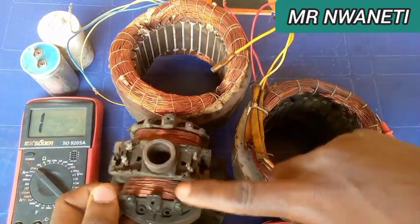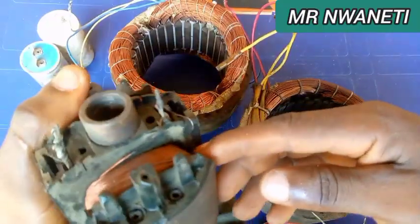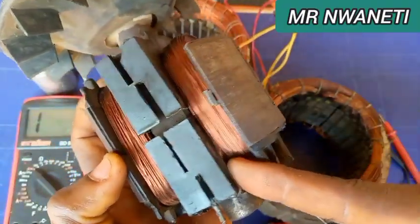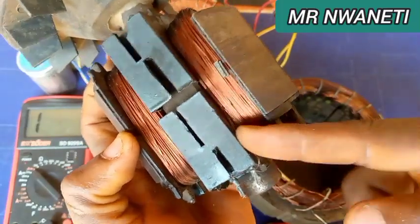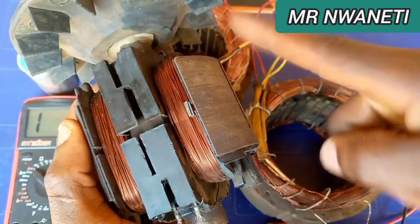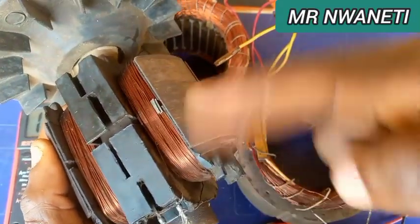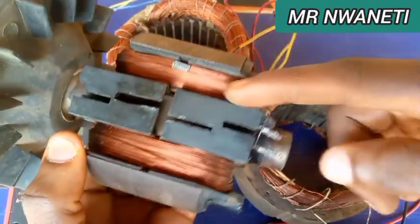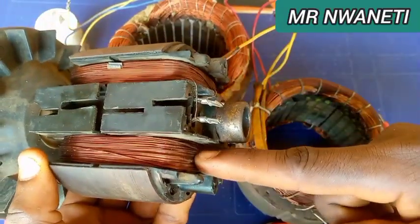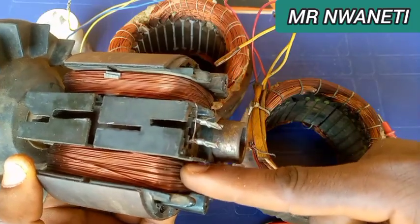So now assuming you want to have more voltage, you can see this is the continuous winding, so you have to loosen it, then maybe wind about 20 turns more, which will give you something about 6 ohms. Maybe 10 turns here, 10 turns here, so that it will be 6 ohm resistance here and 6 ohm resistance here.